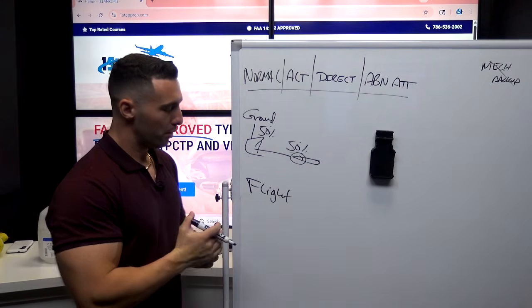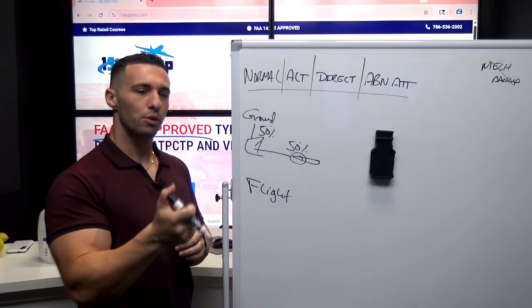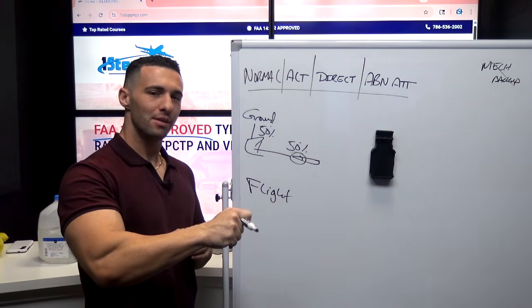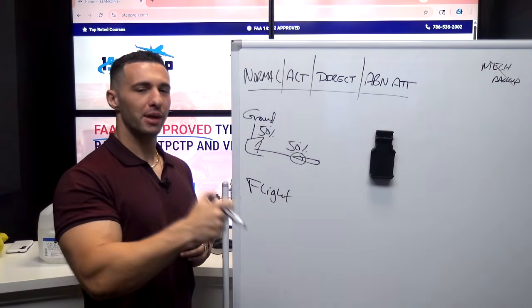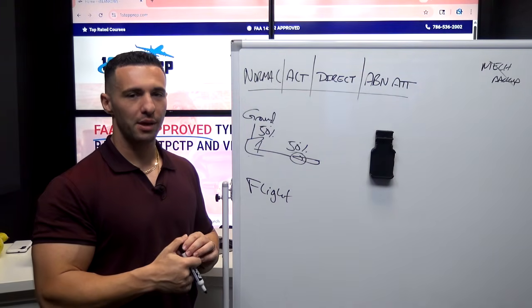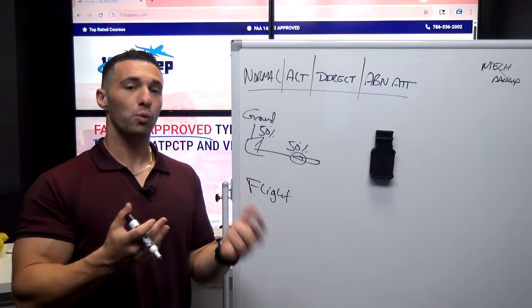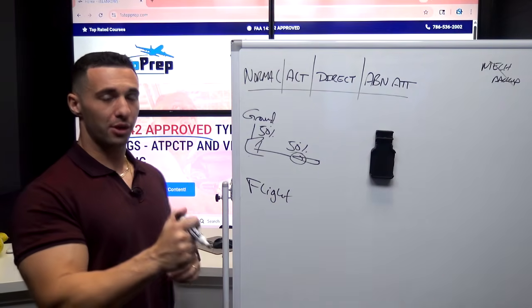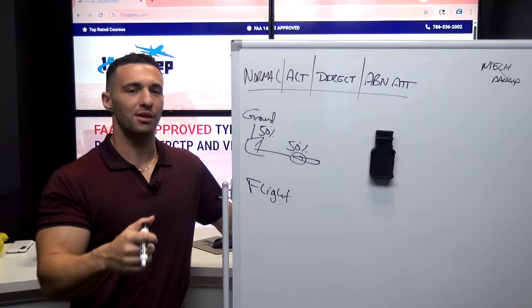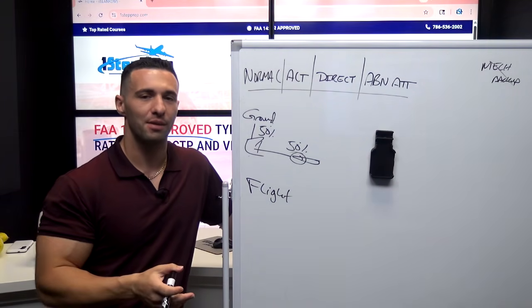And in flight mode, like we just covered, I do very much have G-load and roll rate. The roll rate, similar to G-load, is not a direct communication, but it's a command to roll the aircraft at a rate proportionate to whatever you're commanding. And so a full side stick deflection is effectively 15 degrees per second.